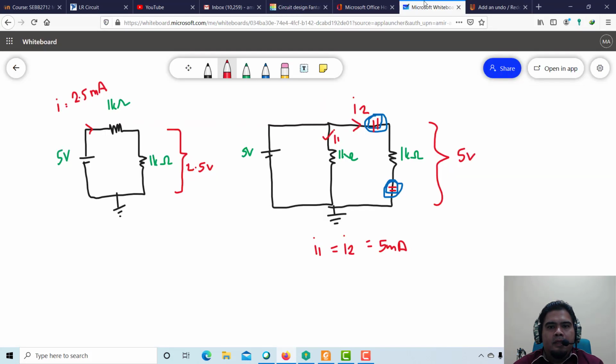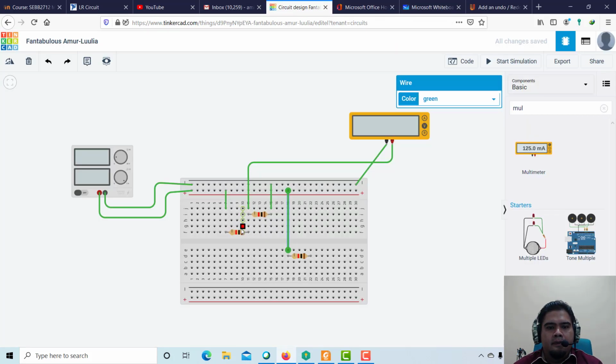After that, if you go back to the circuit, row number 18 is also connected with R2, the first lead of your R2 there. So then you can have your R2. Again, you just click this resistor, Control C and Control V, and you get your R2.